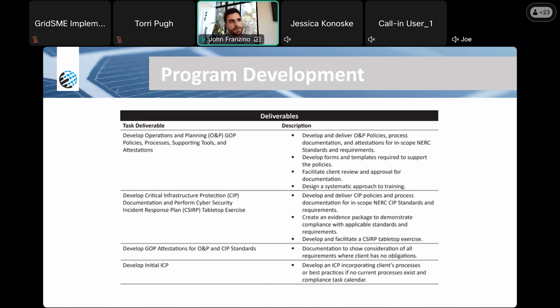So one thing you must do as part of your compliance program is develop any attestations. We talked about FAC-3 vegetation management earlier. If you don't have more than a mile of gen-tie, great, it's a quick attestation with a little supporting evidence from the LGIA or something showing the length of the gen-tie. Good, now we're done. That's all you need to do. But there are usually going to be a handful of attestations that need to be developed as part of the initial program stand-up.